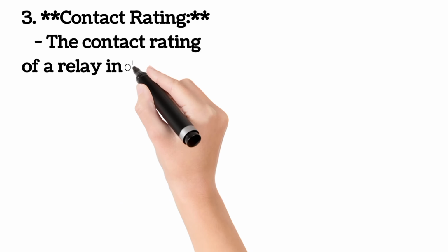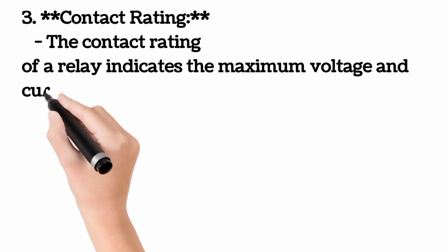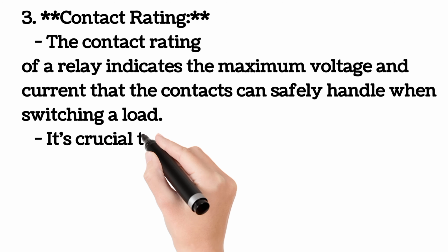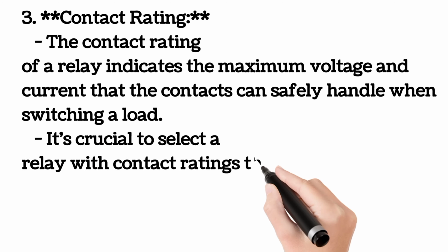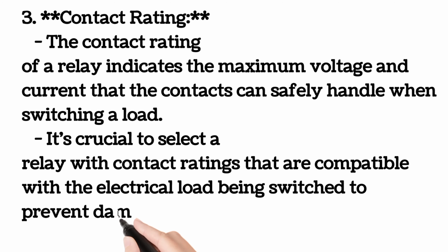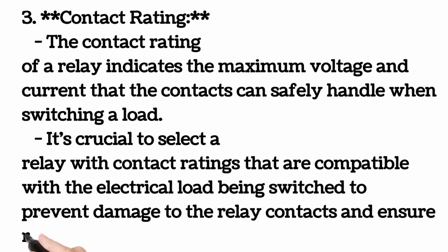The contact rating of a relay indicates the maximum voltage and current that the contacts can safely handle when switching a load. It's crucial to select a relay with contact ratings that are compatible with the electrical load being switched to prevent damage to the relay contacts and ensure reliable operation.